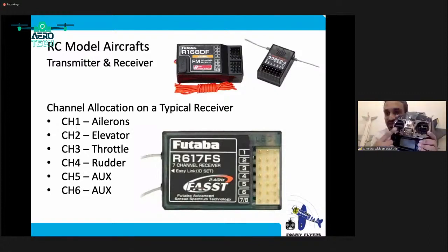That means this is at 0 and this is, let's say, 100, right? So if you have connected the thrust connector onto this, that means this is at 50, right? So this is 0, this is 100, this is at 50. As soon as you connect it, if the transmitter is also on, you are basically telling the ESC that the throttle is at 50%.